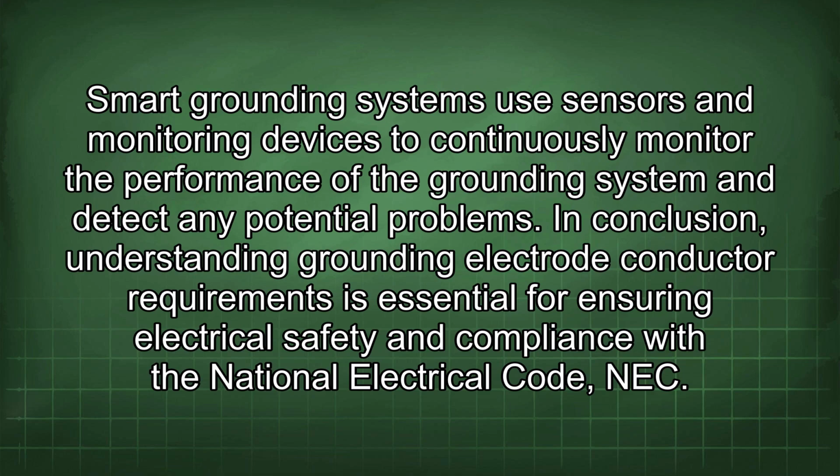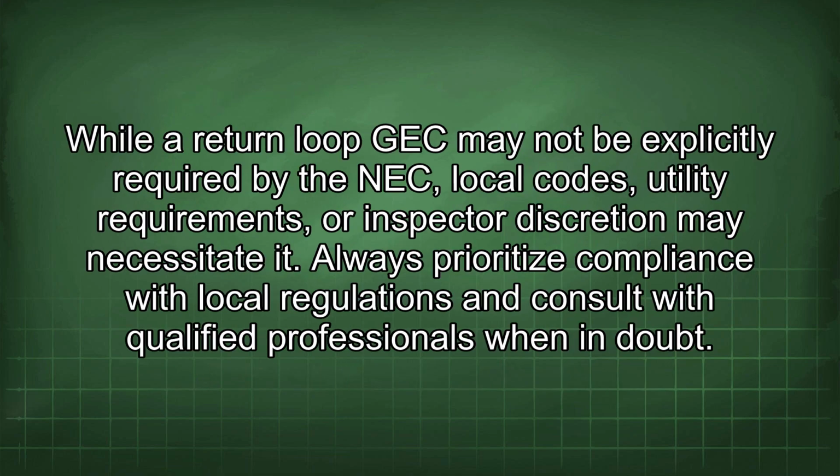In conclusion, understanding grounding electrode conductor requirements is essential for ensuring electrical safety and compliance with the National Electrical Code (NEC). While a return loop GEC may not be explicitly required by the NEC, local codes, utility requirements, or inspector discretion may necessitate it. Always prioritize compliance with local regulations and consult with qualified professionals when in doubt.